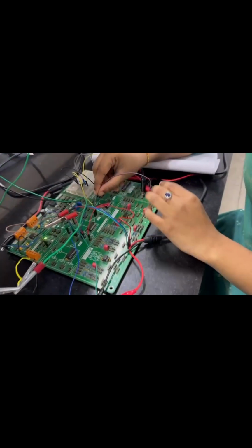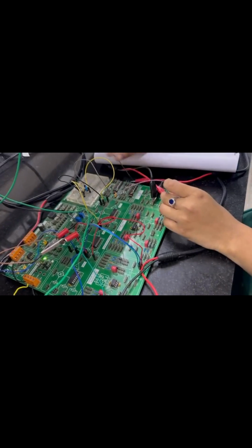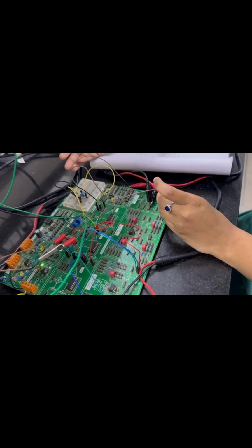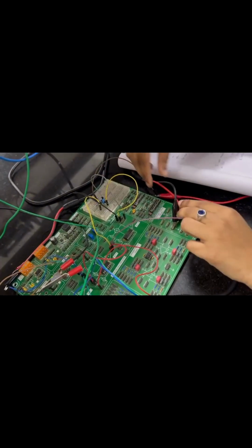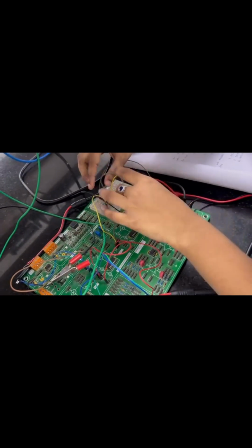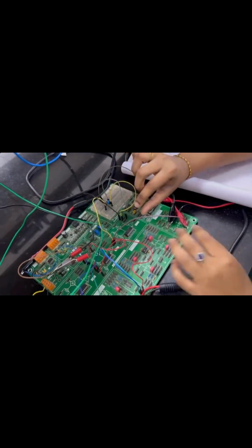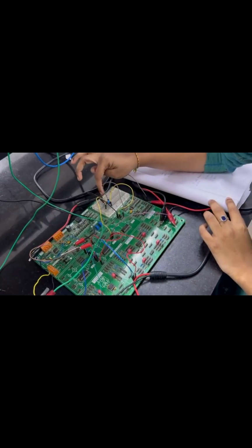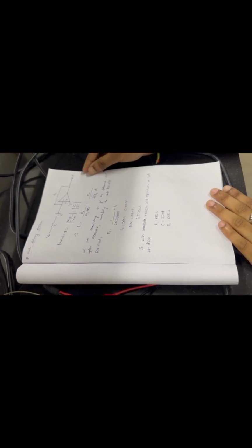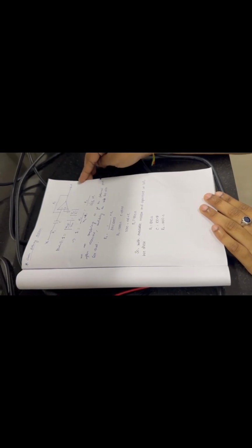And we can see the description of the differentiator based high pass filter. For this, we connected the output of the analog multiplier as the input of the differentiator circuit. This differentiator circuit is connected by referring to this. The power supply pins, output pins, and input pins are connected to the respective pins, as you can see. This is the power supply, this is the output, this is the input wire, and these are resistances and capacitance. Actually, the cutoff frequency, which is 1 by 2 pi RC, is approximately 15,000.